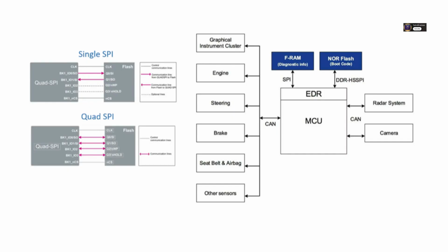Simple enough. Okay, read seems straightforward. What about programming? You mentioned that's trickier. Yeah, programming a page needs care. This is where things go wrong often. To program a page, say up to 256 bytes on NOR flash, first crucial step, the sector containing the page you want to write to must be erased first. If it's not already erased, all 0xFFs, you need to perform a sector erase operation on that 4 KB sector before you try to program.